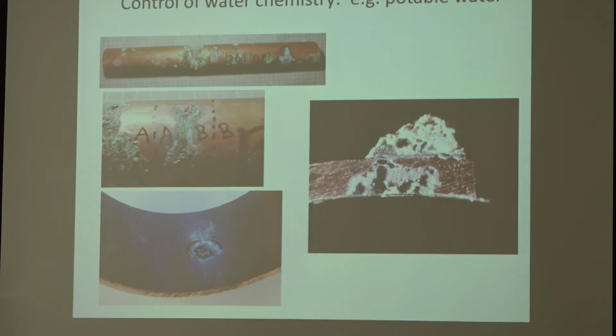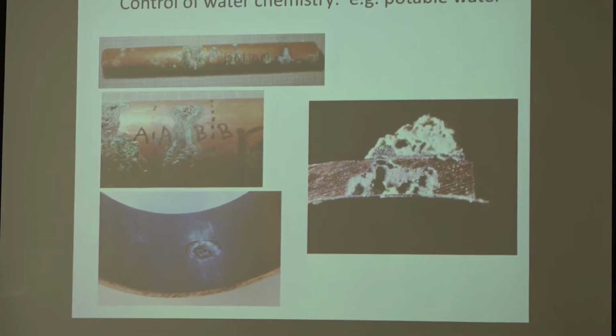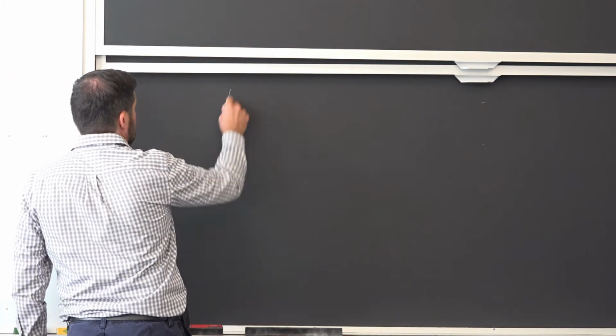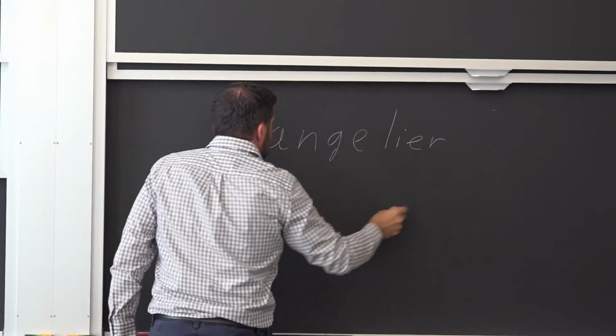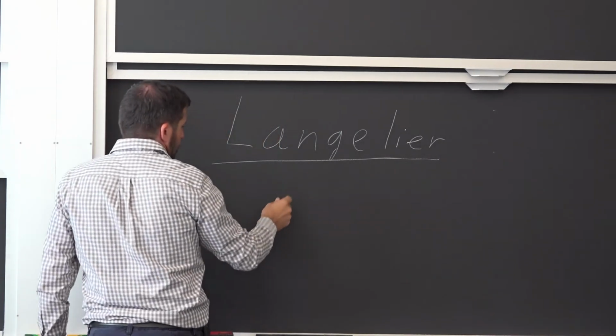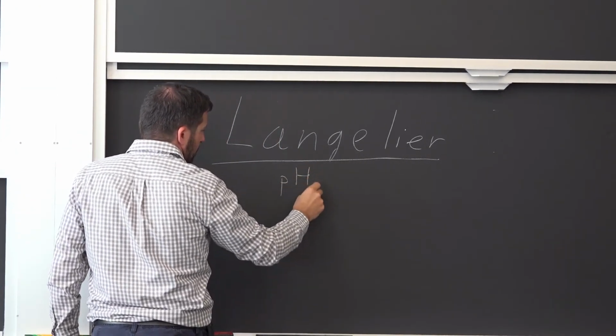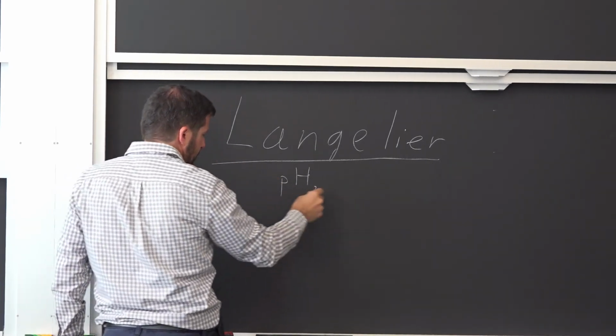Any question on pitting corrosion or this example? Yes? So what property of your water would be most dangerous? Very good question. So what is in the water that affects the corrosion, I believe is the question. A common way to look at it is the Langelier index. And there are other more sophisticated ways, but let's say we have Langelier. It's a relatively simple equation. You can look it up. It takes into account pH. It's going to take into account the alkalinity.